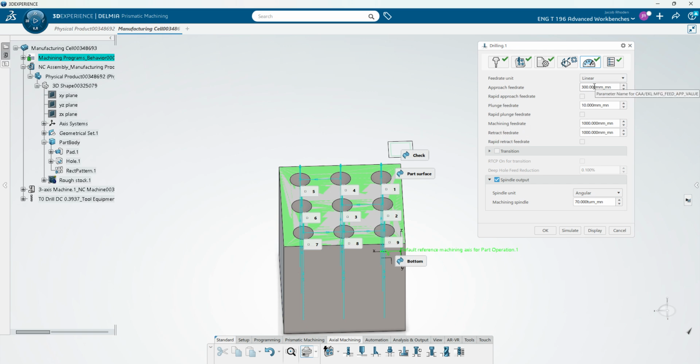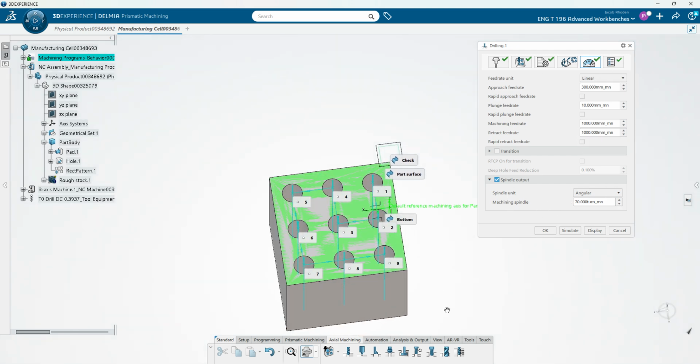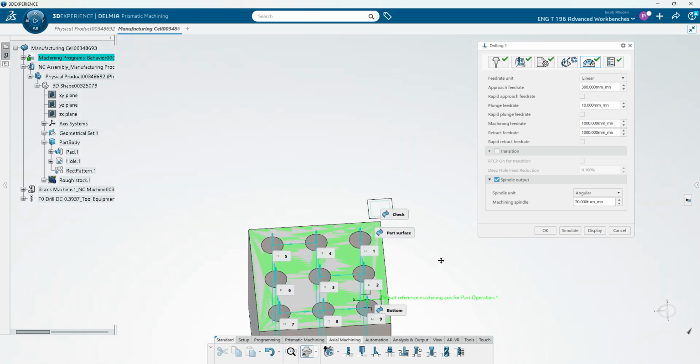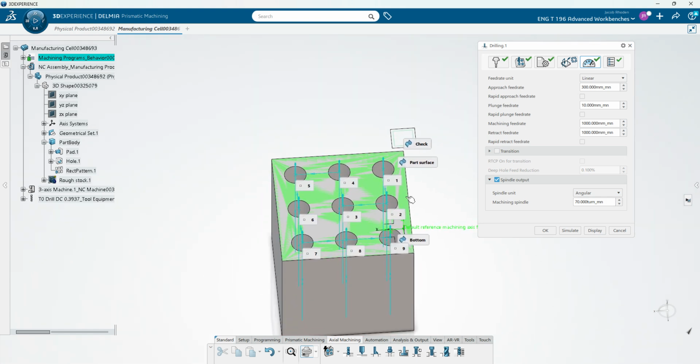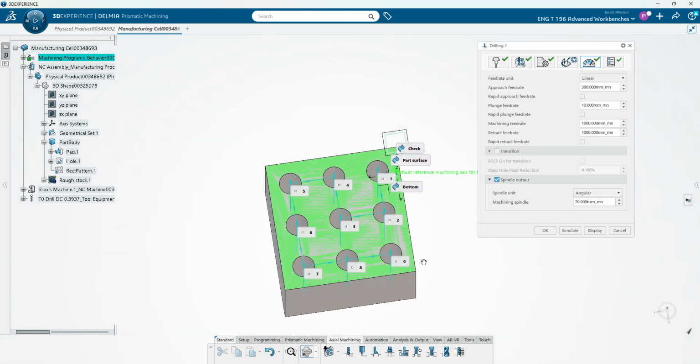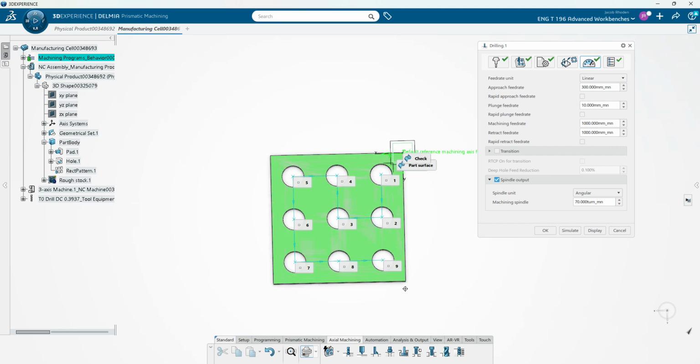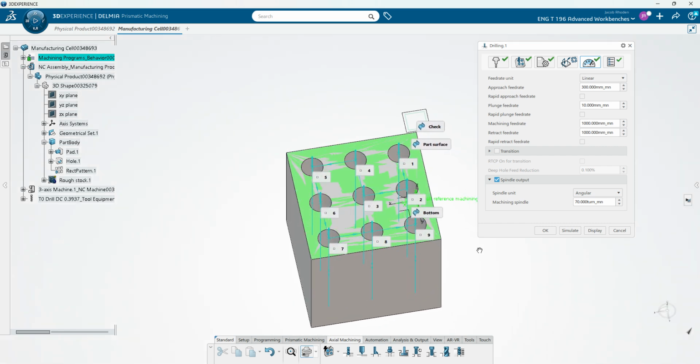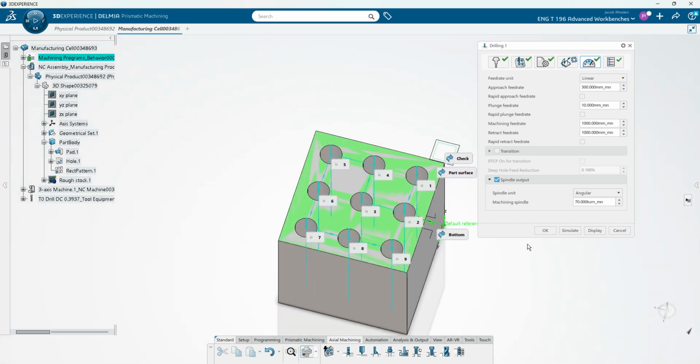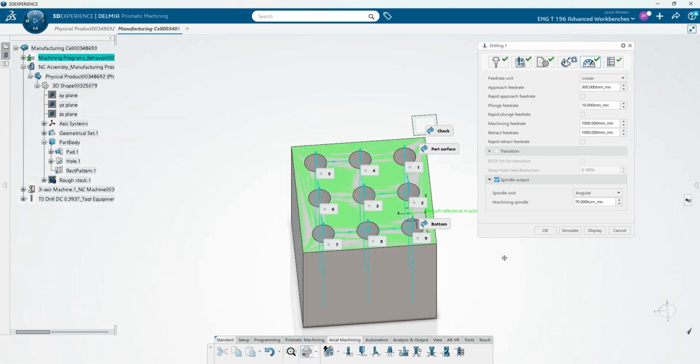We have our feeds and our spindle output, which I believe is different than what we had last time. For the kind of speed you have, if it's not, then you could manually just calculate with your materials and the proper tables, I think, which are all in something like the Machinery's Handbook, or you could just use a machining calculator to find, based on the material, what speed and feed you would need to make sure that you're drilling that hole with proper chip clearance.